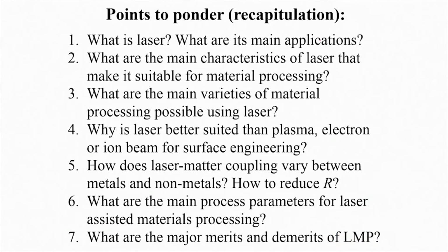What is good about laser is that the coupling efficiency is very fast. The way the incident laser photon gets converted into lattice heat takes less than a nanosecond, so an extremely fast process. The other good thing about laser is that the heat deposition profile is exponentially decaying, so maximum heating is at the surface, and only within a few micrometers from the surface the temperature falls to room temperature. So essentially you are dealing with a very small volume of the solid at a time, and the rest of the bulk will all be at room temperature. So you are affecting a very small volume.